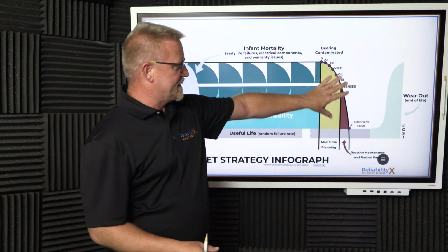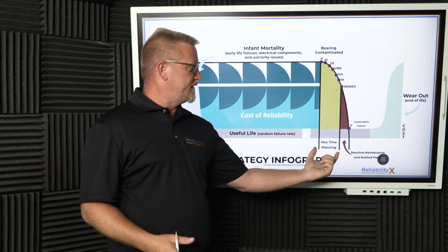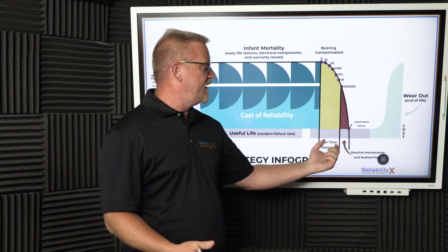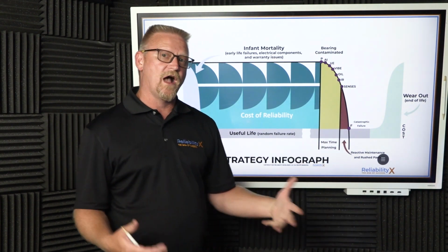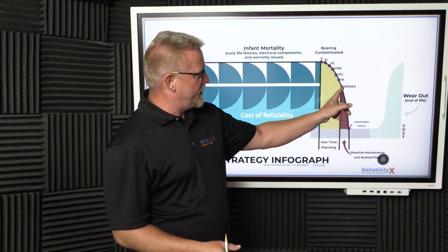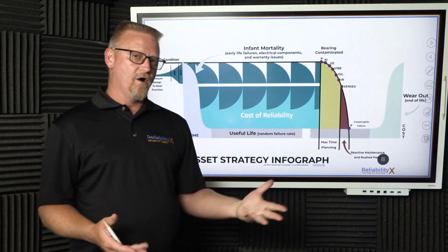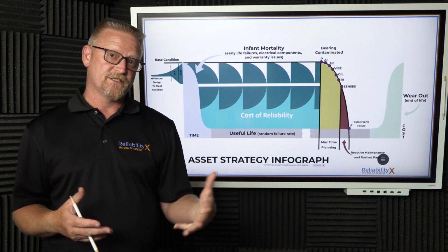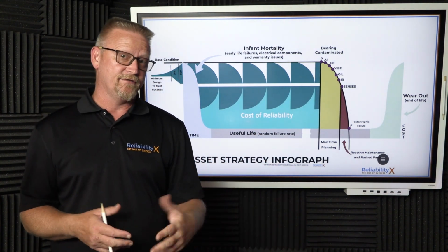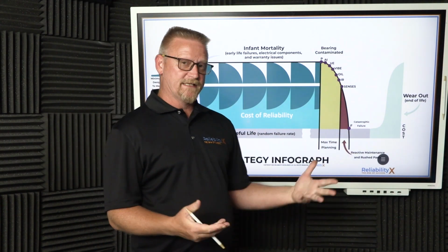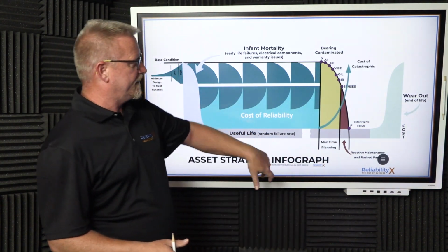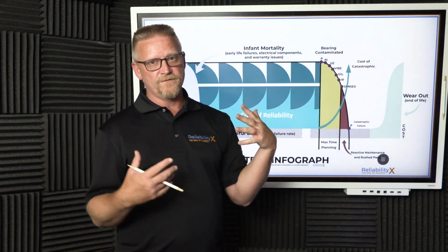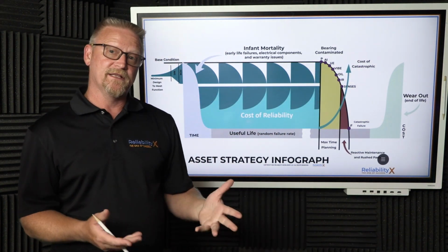And so we utilize these technologies to live in a proactive mechanism, or at least to give us enough time to properly plan and eliminate the catastrophic failure. Once we live within our senses, we are living within the reactive maintenance domain. And so once we are just using our senses, we don't typically have enough time to address the failure without the catastrophic event. Once the catastrophic event occurs, again, that cost goes way higher than it typically would be to restore to base condition.